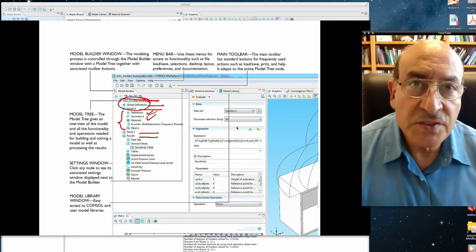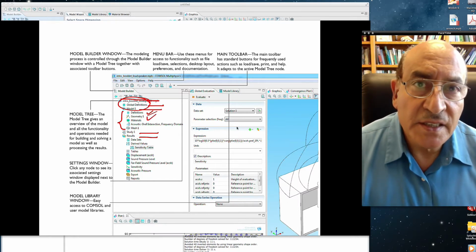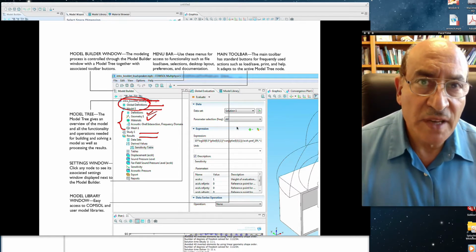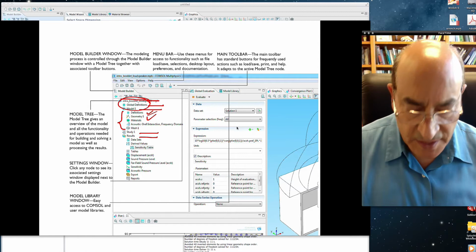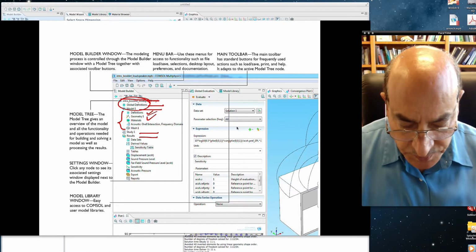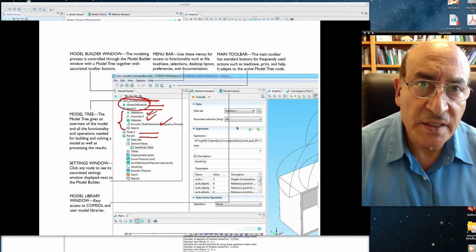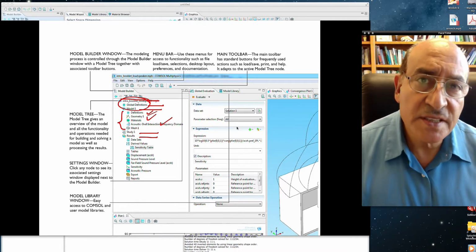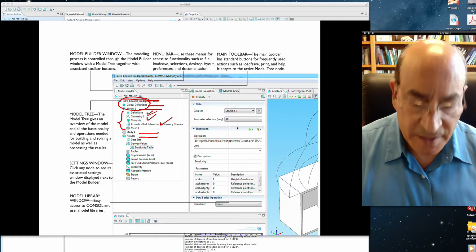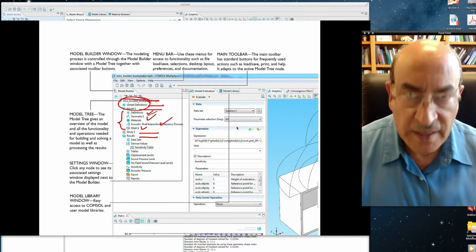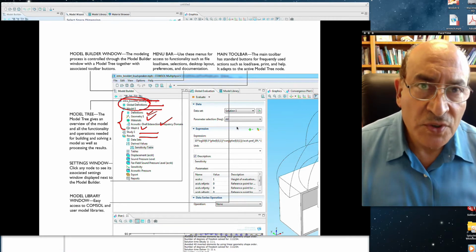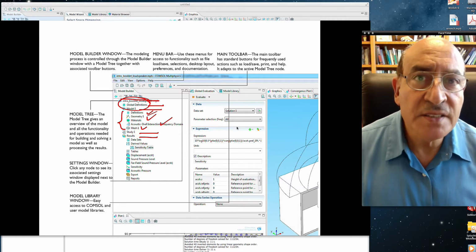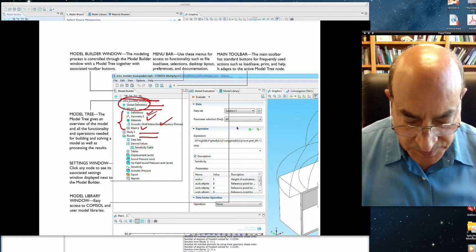And then in addition to this, we have a materials child node that we will define. Material, we can select it from a library, or we can define the properties ourselves. We have also the physics that we will study. Here it says acoustics, but we are going to study solid mechanics. And then finally, the last child node is called mesh, in which we're going to define how coarse or fine the mesh is for better resolution of the results.